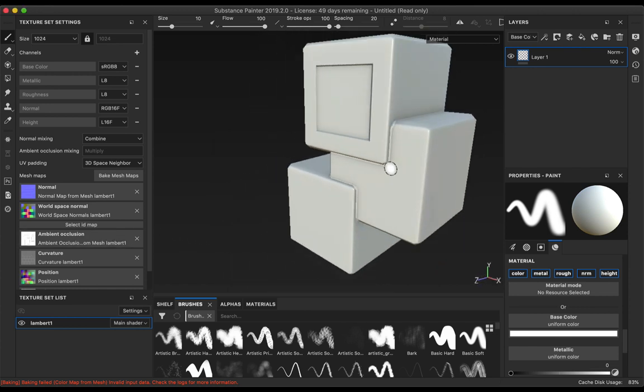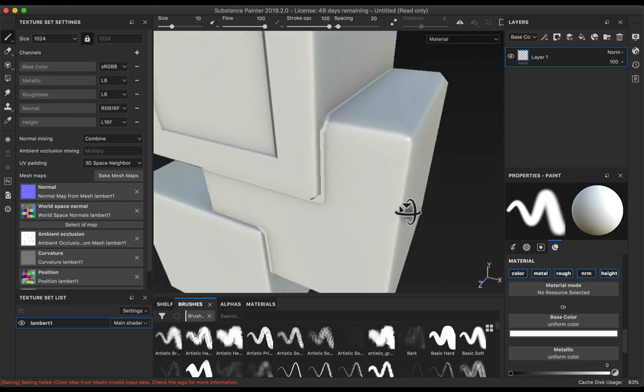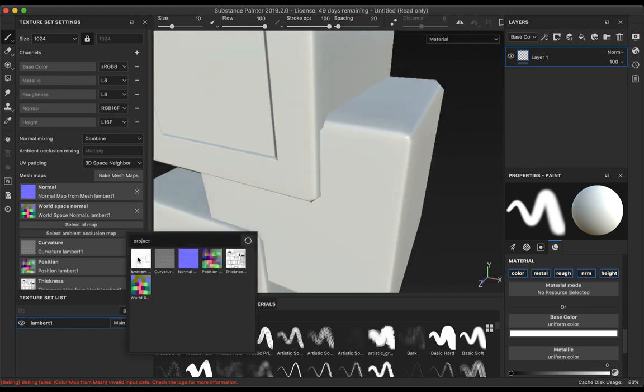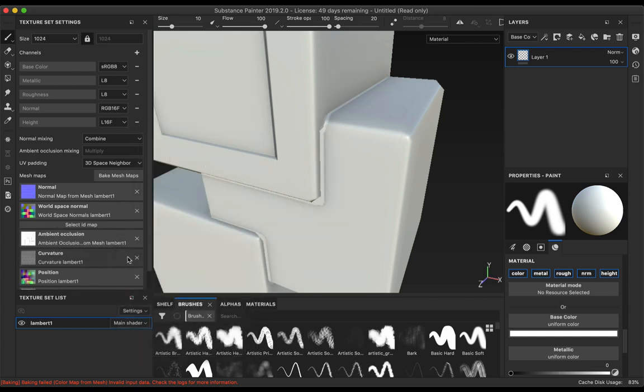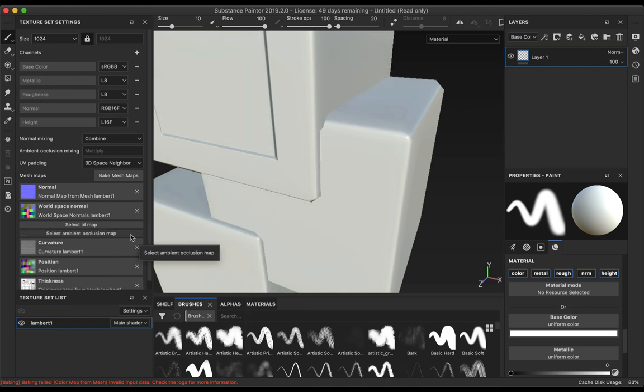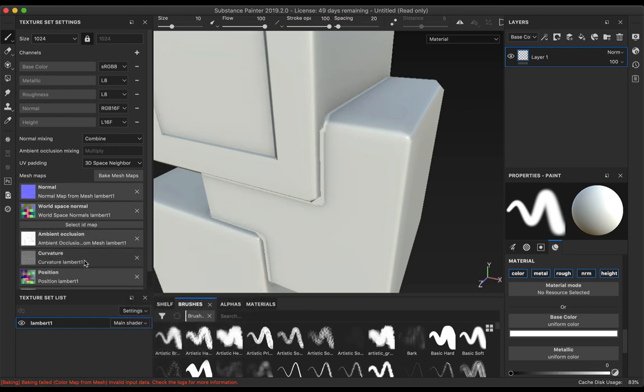And the ambient occlusion is always going to cast back. It gives you that shadow. So you know, ambient occlusions are grayscale textures. After I'm done with my base color and I'm totally done texturing, I can bring this ambient into Photoshop and clone stamp out all of these shadows. You need an ambient occlusion. There is not really a way to fix this. I would not worry about it if it is only happening in the ambient, and it's very easy to test that out by just turning it off. If there's no problems with the normal or with the curvature, then you're good.